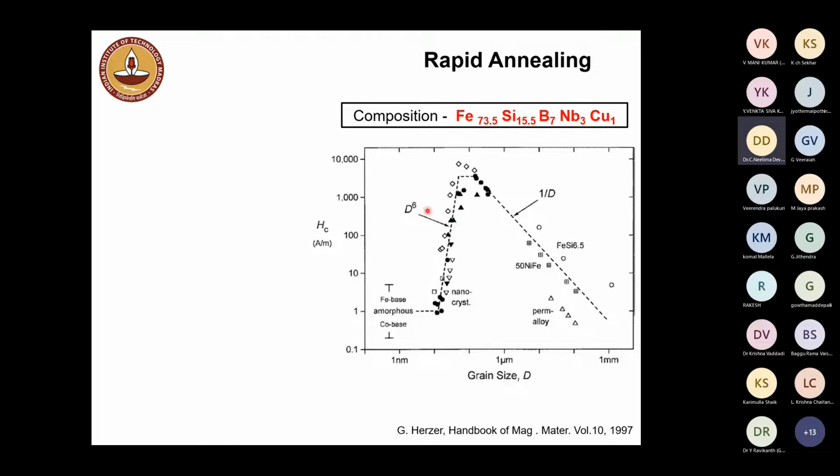The grain size, as it decreases, the coercivity decreases at the rate of 10^6. That means for each nanometer decrease in grain size, you can have 10^6 times decrease in coercivity, which is therefore going into the soft magnetic regime again and making this more attractive. So in order to produce, on an industrial scale, a nanomaterial having a grain size of 5 to 10 nanometer, we really require fine nanocrystalline grains.